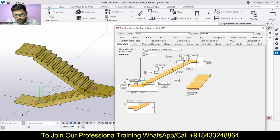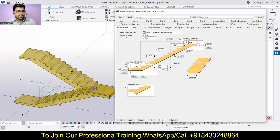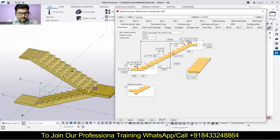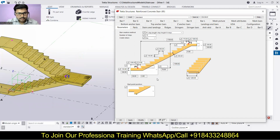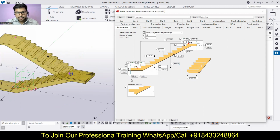Then what is the next thing? This is 200. That is good. Then this should be 1300. I will click on Modify over here so that it does the modification at this place. I'll also show you how you can move this, because we have to finally move this whole staircase so that it comes into position. Now you can see it has been modified in the manner I wanted. Now I will also extend the slab and everything, but for that just wait for a while.